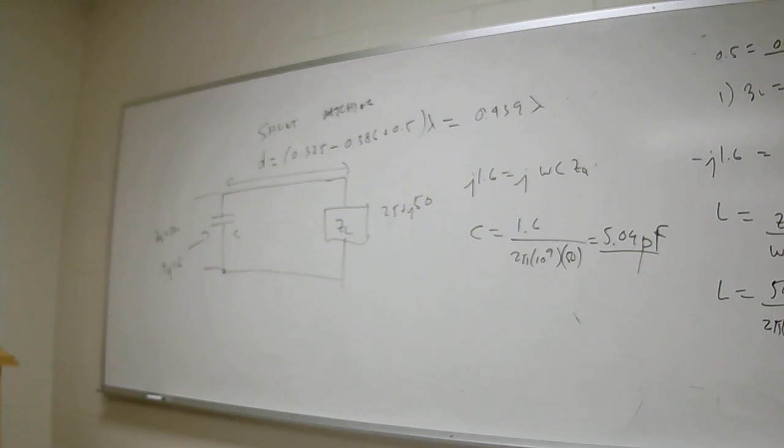Cut the lead lengths as short as possible, because the effect on total inductance, both external and internal inductance, of a lead that long at a couple of gigahertz is maybe larger than the inductor that you actually need for the matching. You've got to be aware of that. Same with capacitors. There's all sorts of stray capacitance between leads and inductance. Just be aware of that for now.